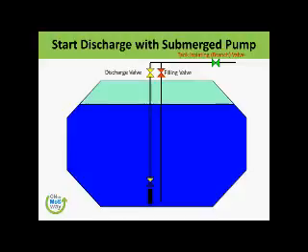So what we will have to do, we'll have to start the small pump or the stripping pump. And of course, we never normally discharge 100% of the cargo. We retain some of the cargo in the tank as a heel. The bunker barge will also retain a certain amount of cargo to keep its tanks cool, because all the heat ingress from outside, from the insulation, etc., will let certain molecules of the liquid evaporate, and again the tank heat is in those molecules which are evaporated.